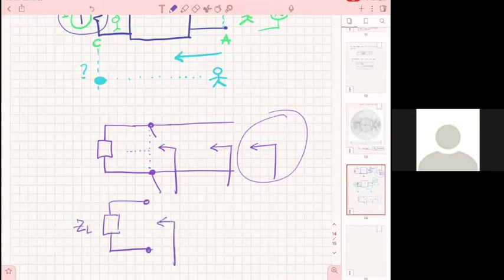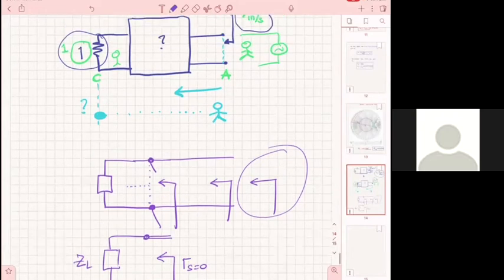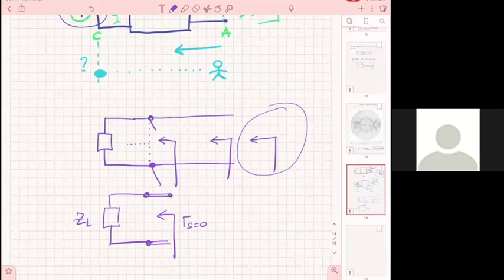So I see a 0 reflection coefficient here. The best way in this one is to start moving along a line and find the right place for you to put a stub, but you do that, you move towards the source as you are going further away.